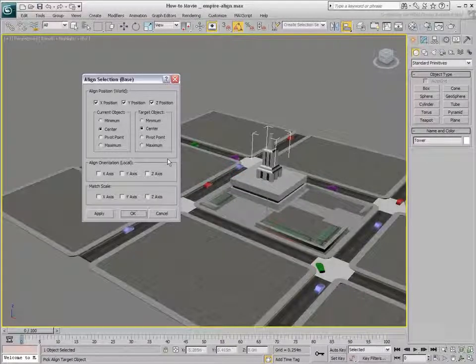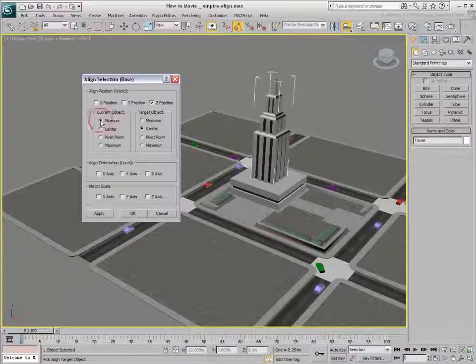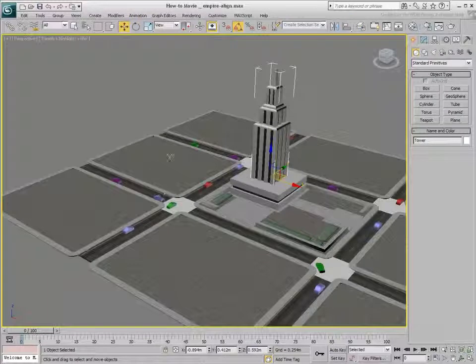In such a case, you are looking at a height-only translation based on the Z-axis. With the Z-axis alone enabled, you can force the minimum value, the lowest Z-value, of the tower to be aligned with the maximum value, the highest point, of the base. Usually you do not need to exit the dialog to force changes.